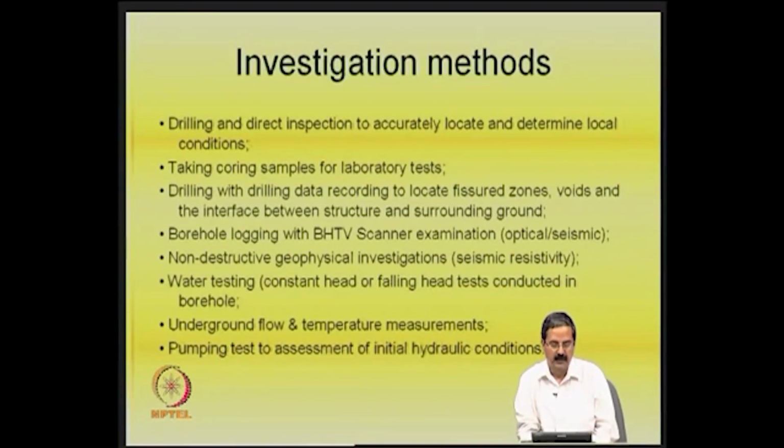So, people are also employing non-destructive geophysical investigations, seismic, resistivity, then water testing. Particularly you can do this, for example, if you are trying to find out the permeability of the rock or a soil, because the objective is essentially to find out this pore size here. If the pore size is bigger, you would like to see what its impact is and how to use a proper grouting method here. So, the permeability is quite important.